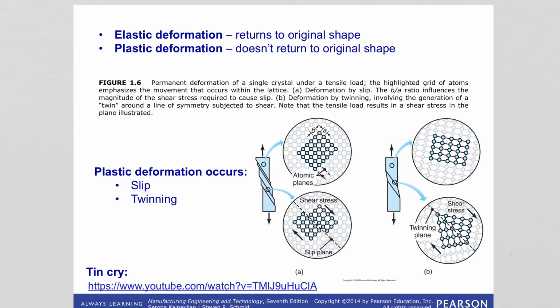And the question is, how does the plastic deformation actually happen inside the material? By two ways. One is deformation by slip. The other is deformation by twinning. Slip is basically, by the application of, of course, you apply tensile stresses, deforming the material, and the shear stresses generated due to these tensile stresses.